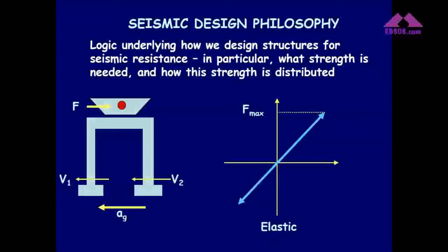What I mean by elastic design, you can resize your columns and put reinforcements in these structural members in order to remain in elastic phase without any ductility demand, without any damage in the structure. But this costs a lot. And in engineering wise, what we would like to do is to keep the costs at a minimum level and to achieve the best performance from the building. So this seems not feasible for